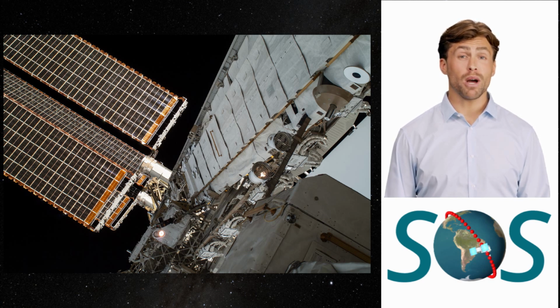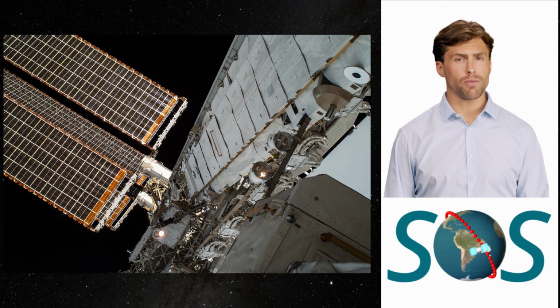For planets further away from the Sun, the power density is lower because it drops by the square of the distance from the Sun. Of that 1,400 watts, only an average of about 700 watts per square meter reaches Earth's surface. Losses are due to reflection and absorption in air, caused by clouds, dust, fog, and smoke. In dry areas with high altitudes, the average goes up.